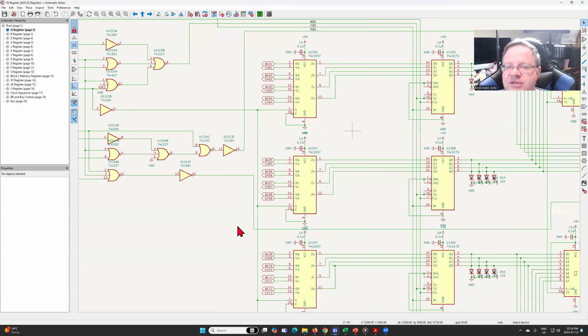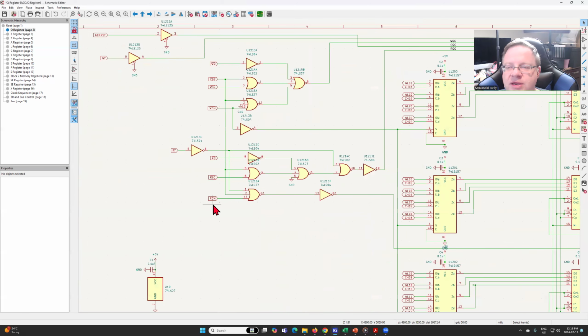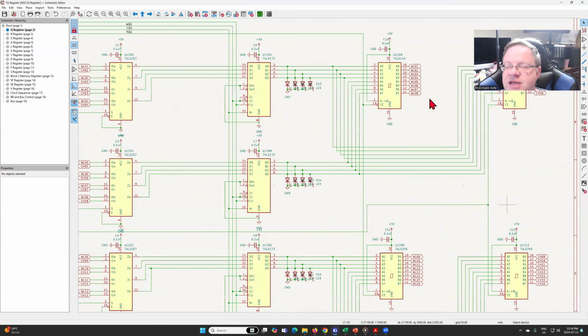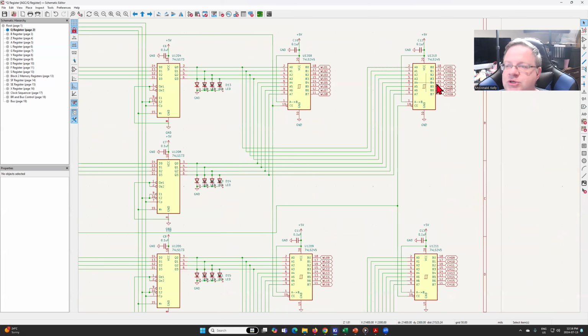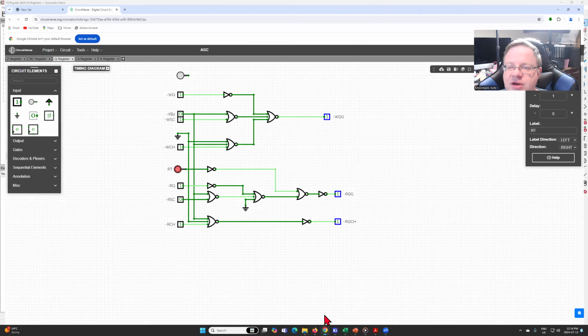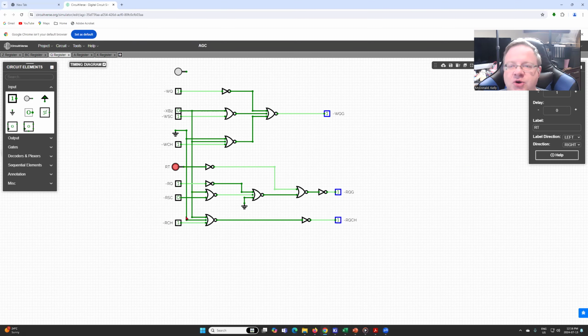Now we also have the scenario where we need to push data out onto the channel, the I/O channel bus. This is where we have this signal asserted, also with the XB2 address, and then the write timer as well. And that flows to the second set of octal transceivers, which are connected to the channel bus. That allows us to push data out onto the I/O channel rather than the write lines. So that's the layout, and we've created a little bit of a simulation here to show how it will work.